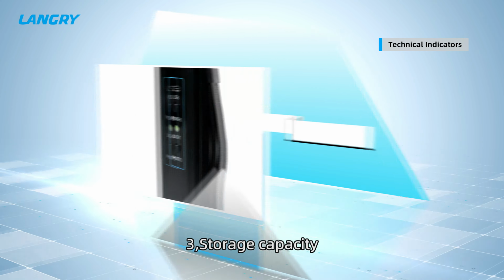2. Display area. This area displays the crack width in real time, and displays the object number, crack number and measure point number at the top of the screen. 3. Operation area. This area is located at the bottom of the screen, and is composed of 5 functions, namely, new object, new cracks, black white, OK, and back. When continuous crack width detection is performed, the system defaults to the measurement point number plus 1.